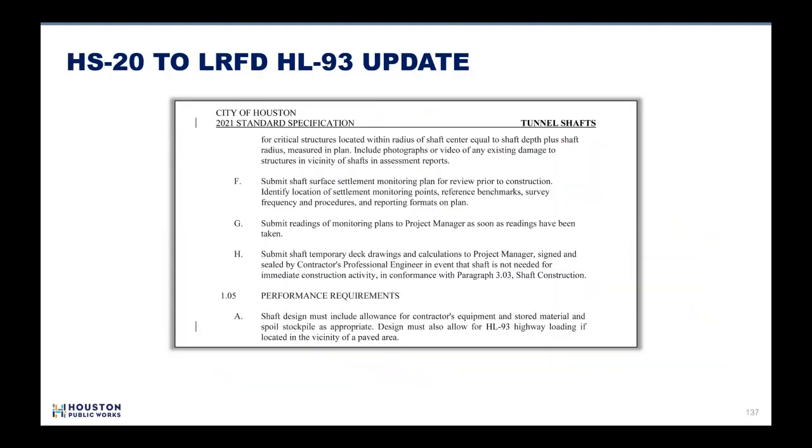As a part of improving the city standards, it was decided to move away from the AASHTO HS20 loading criteria and require LRFD HL93 AASHTO loading criteria. Almost all documents have been updated to be consistent. For example, major revisions to the submersible lift stations guidelines are being undergone. Thus, HS20 has not been updated in that document. Items such as manhole covers, which are to conform to HS20 loading according to AASHTO M306, shall be designed according to that governing document.